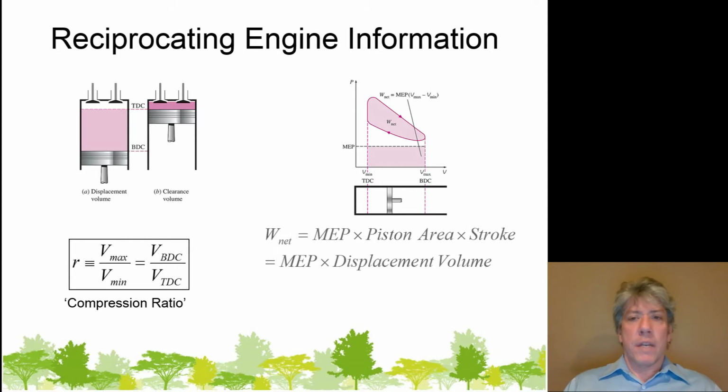Now, what about mean effective pressure? If you've ever been around race cars or compared engine details, you've probably heard the term mean effective pressure. Now remember, on a PV diagram, the area enclosed by the cycle represents the net amount of work done in one of the cycles. So you can see the real process up there that has, not sharp edges but smooth edges all the way around, and there's a net work enclosed in it. Well, that net work is a certain amount of work, right?